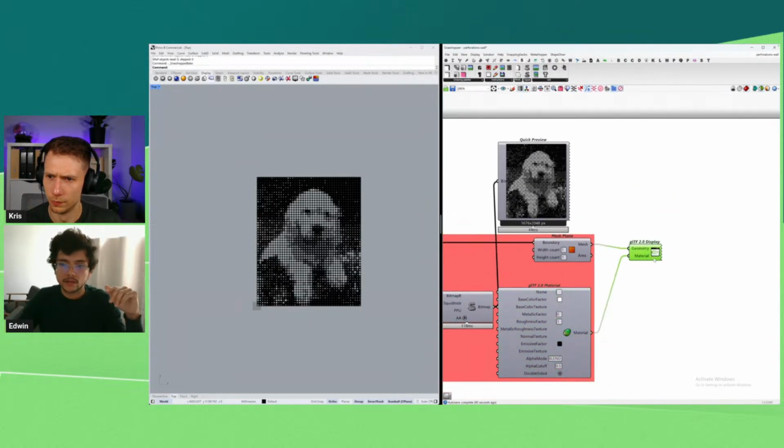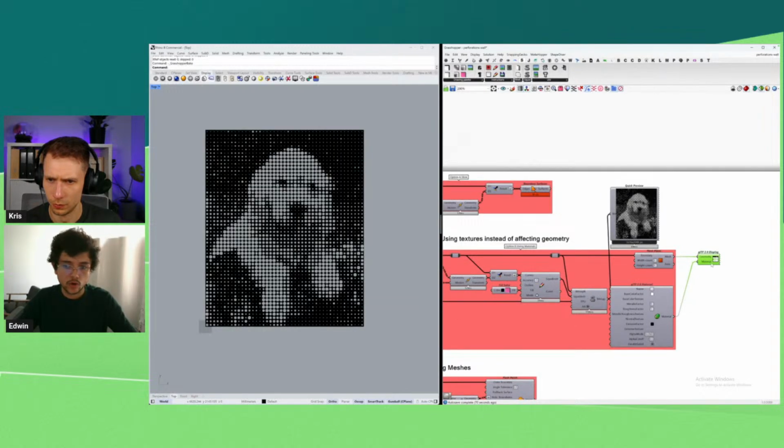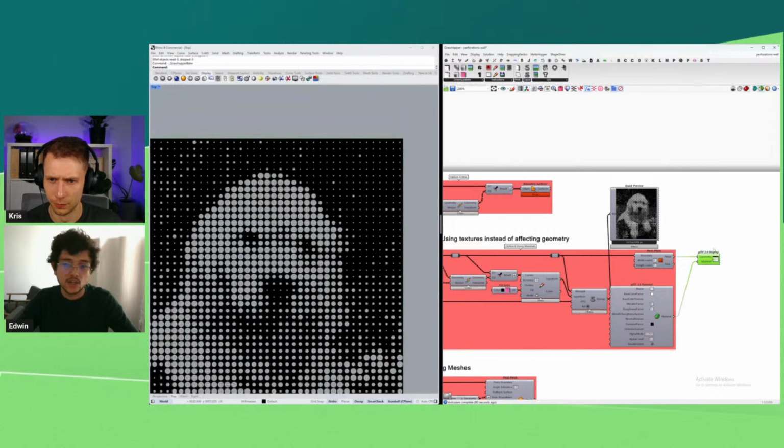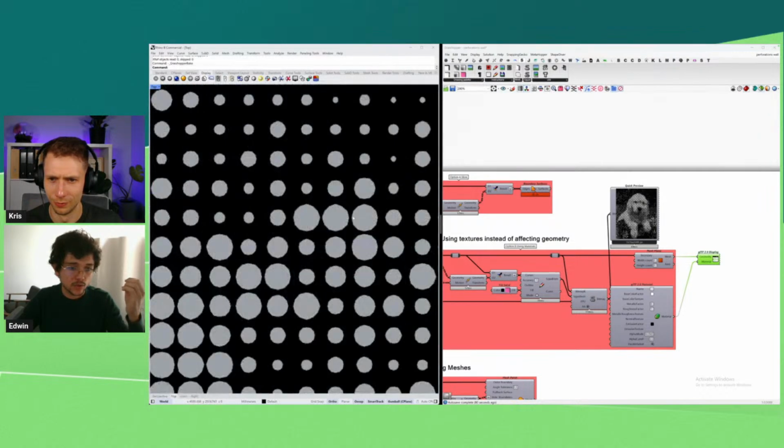And that creates then this result. So actually, if I check this, if I press Control M, it is going to show me the lines of the mesh. In this case, you can see that I just have the exterior one. So basically, this is just a one face mesh. That's it. That has an opacity map, so it fakes transparency so that we can see through.